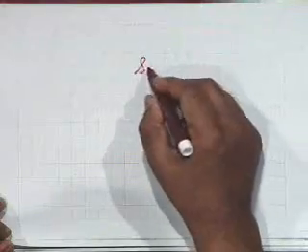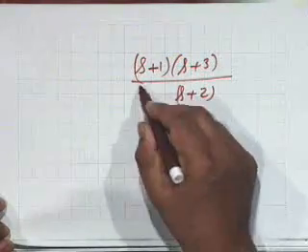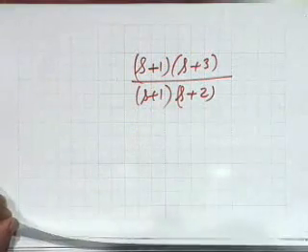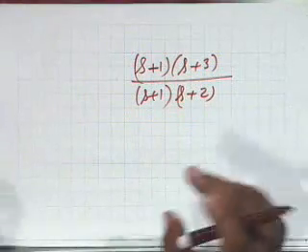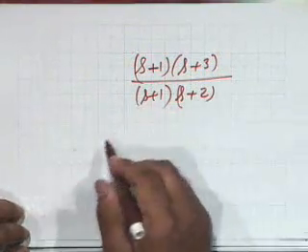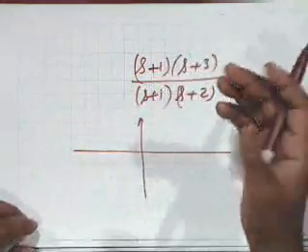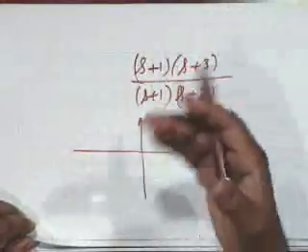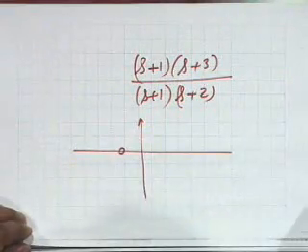So suppose you have coincident poles and zeros, then how do we depict the picture? If we have coincident poles and zeros, why? Okay, that is a good question. Suppose I have s plus 1, s plus 3, s plus 2, s plus 1. There may be a system in which this happens, that a pole and zero coincide. Alright, then what we show is in the form of a picture. If you can discover this, we may not be able to discover this because in the analysis you might have tacitly, implicitly cancelled it. Alright, if we discover this, then we show a 0, and on this we show a pole.